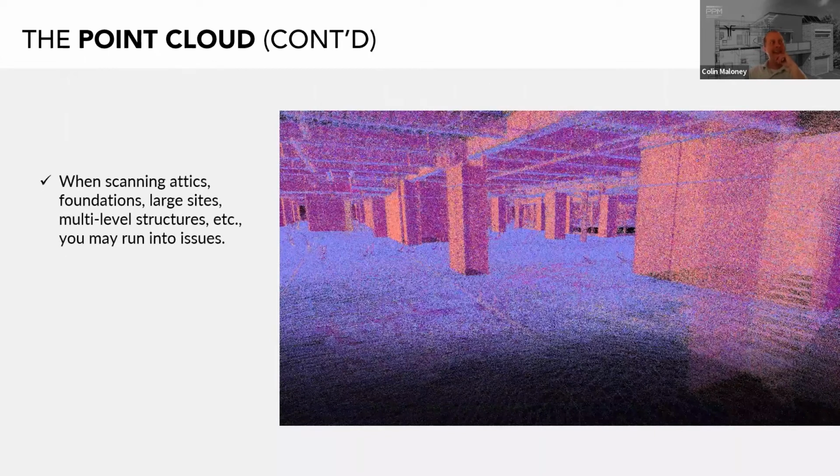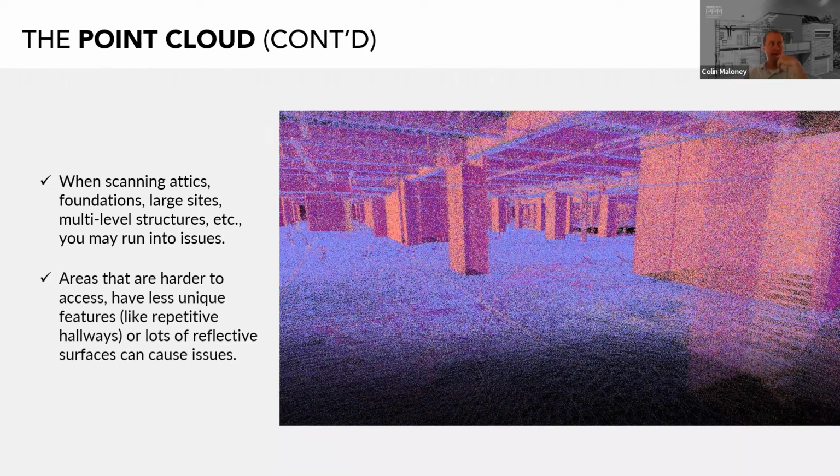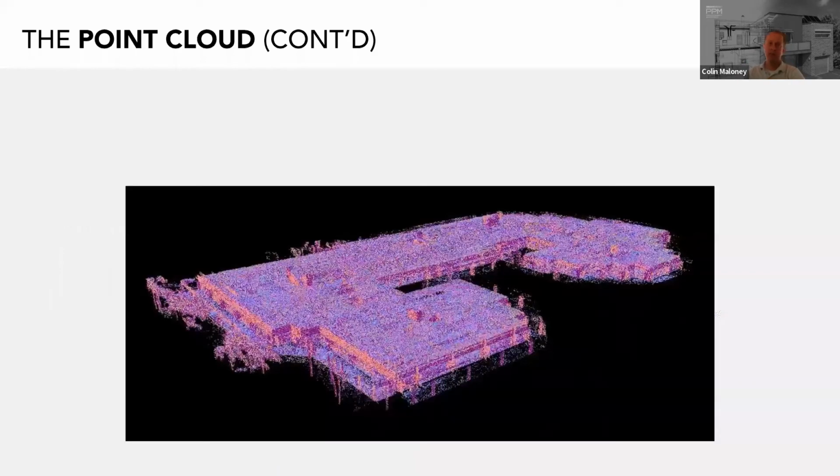When scanning attics, foundations, large sites, multi-level structures, etc., you may run into issues. Areas that are harder to access or have less unique features, like repetitive hallways or lots of reflective surfaces, can cause issues.